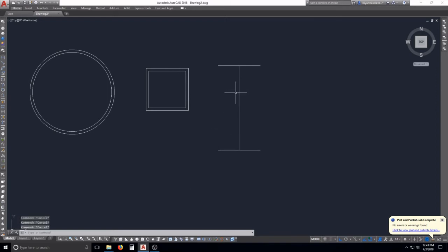Alright, now what we're going to do, we're going to offset these walls 1/4 inch, and then we'll join them all together to make it one big object. So again, offset, quarters defaulted, offset there. We're already in the command, so we'll just do it again. Here, if we do it, it'd be a 1/2 inch, so we want to go back and say offset 1/8 inch, which is 1/2 of a quarter. So offset, and that quick decimal is 0.125, which is 1/8 inch. And then enter. So we're going to go to the right and to the left.